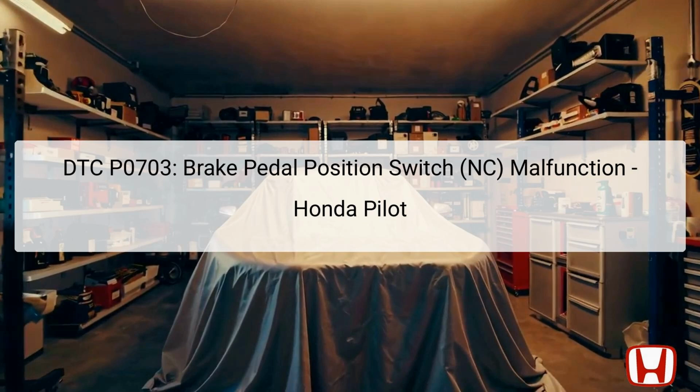When the switch fails, it can lead to driver safety concerns, as the vehicle may not recognize a braking action effectively. The malfunction might be triggered if the brake pedal is pressed lightly for an extended duration while also pressing the accelerator pedal, causing DTC P0703 to store.